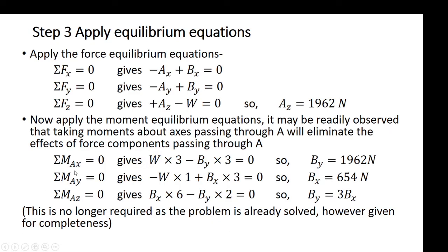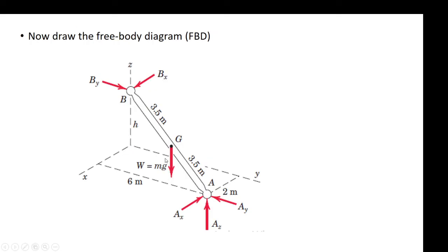So you can easily calculate the moment of all the forces about the x-axis at A. So you can write down the scalar components of the vector equation like this. This you have to do a little bit of exercise. Like that, I can show you one. Suppose Mx = W into 3 minus By into 3. Please mind the sign. According to the right-handed coordinate system, what rotation is positive or negative, you know it is a right-handed system. So now go back, W into 3 minus By into 3. W into 3, so you need to have this distance halfway.